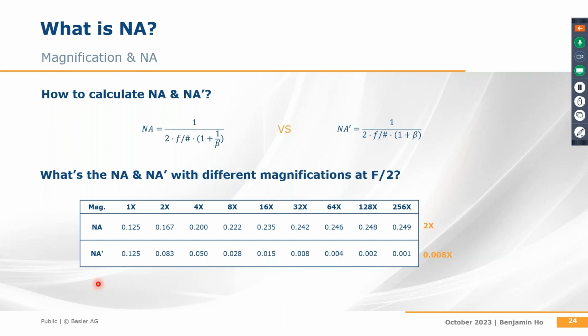We are currently using an inspection device that has a 1 times lens to detect a defect of 20 micrometers. However, the equipment now needs to be upgraded to a system that can detect 5 micrometer size defects. Since the size of the defect has been reduced by a quarter, from 20 micrometers to 5 micrometers, most people think that if they change the magnification of the lens to 4 times, it will be able to detect the 5 micrometer size defect. Does it really work that way?